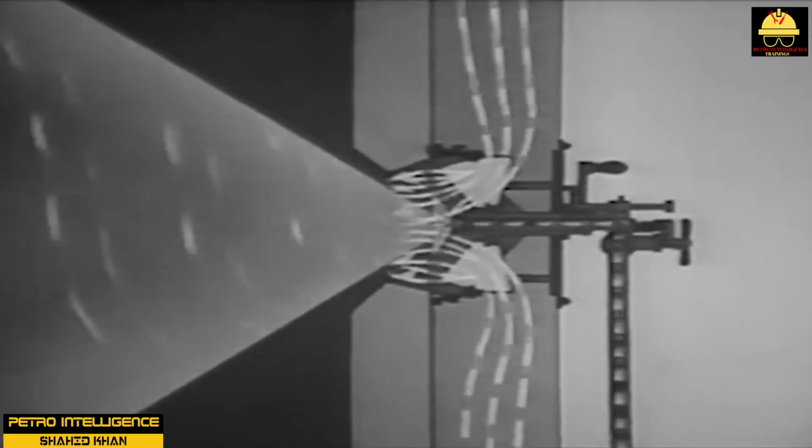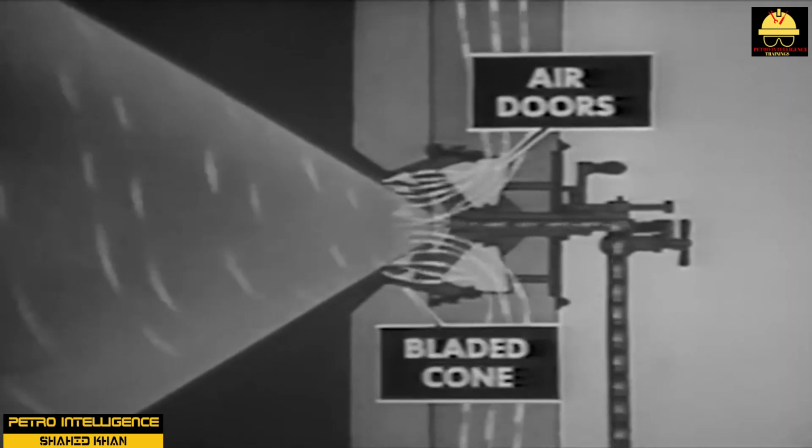Low NOx burners are designed to be operated with lower amounts of excess air than typical burners. The use of tertiary air registers reduces nitrogen oxides in the flue gas stream. The burner uses a small amount of steam to better disperse the fuel and oxygen.